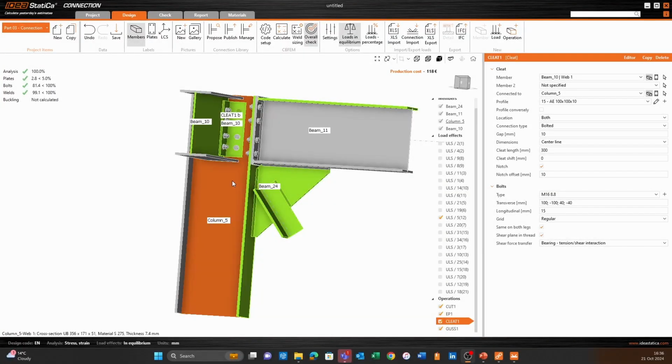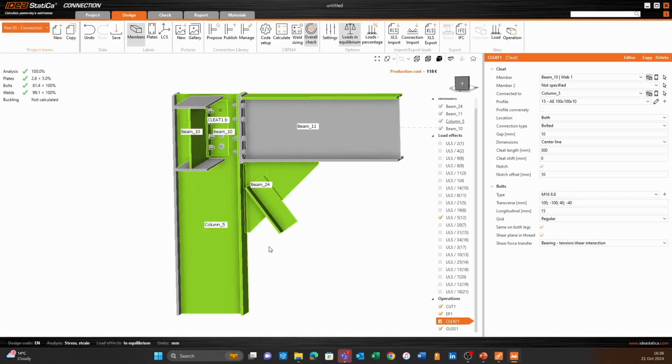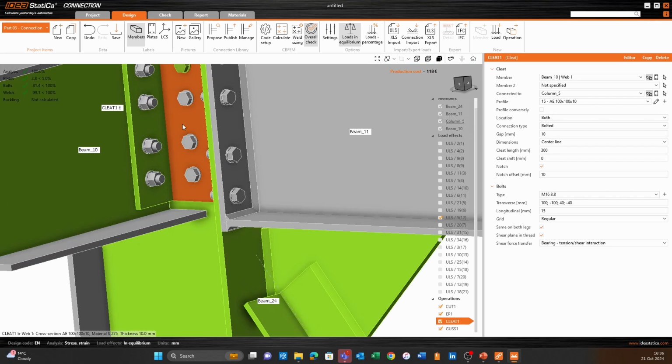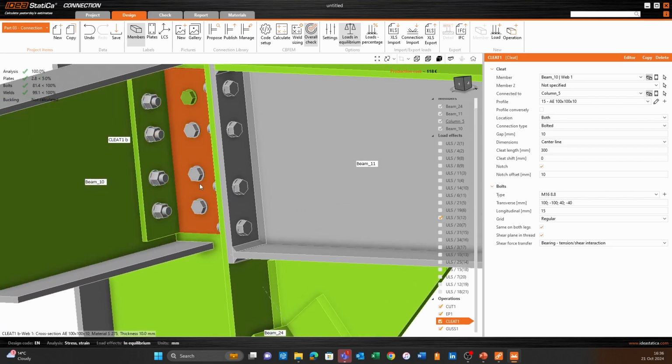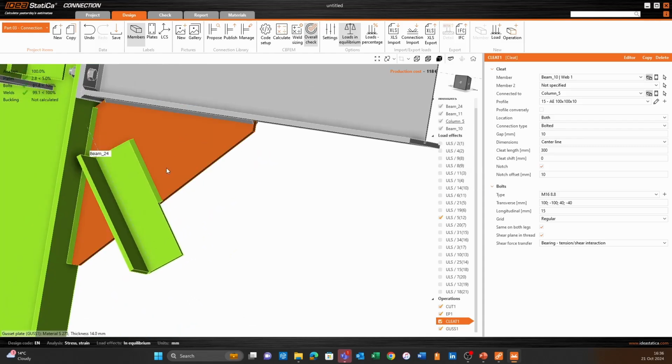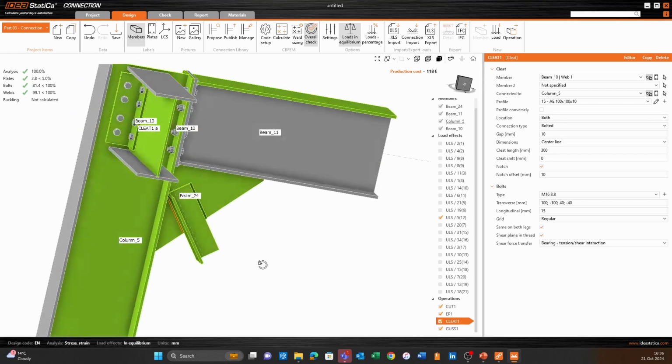And we have liftoff. Look at that. I am so happy with that outcome. So we didn't have to change the size of the cleat. We merely made it a bit longer. We spaced our bolts out a bit better. We increased the size of our gusset and also the thickness. And so we can also increase the length of this weld. We changed the weld size a little bit.